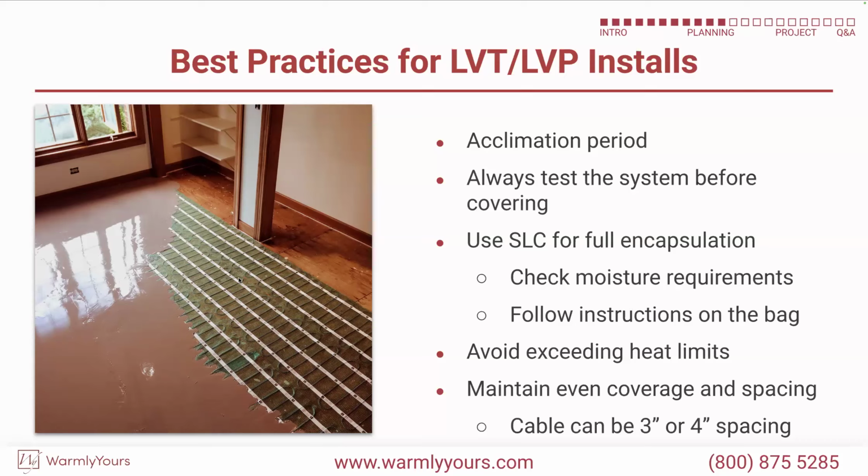So notice on this drawing right here, you can see that the wires are facing down, wires side down. This has been glued in place every 6 to 8 inches, just little dabs of glue to hold it down, because you can see there as we're pouring over it, it's not coming up. It's a nice flat sheen there where it's not raising to the top. If we didn't do that, you would see that cable physically just start levitating up to the top of the pour.